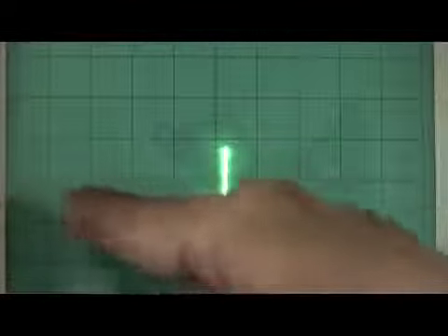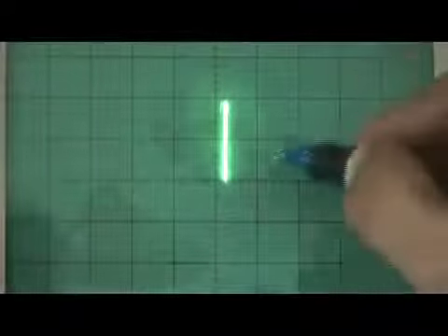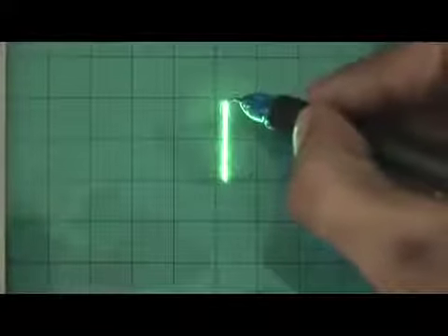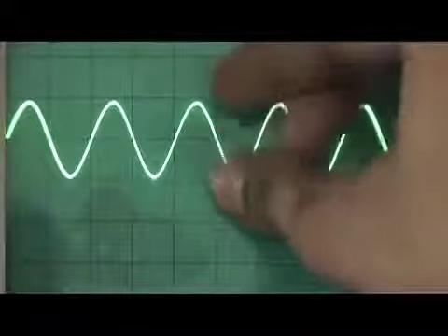Now, this dark black line which has subdivisions is your reference line. Using this y position knob you can move this line and bring it over here so that you can properly count the number of divisions. Now it is here. From here I count, it is complete till here, 1. From here it is 1.2, 1.4, 1.6, 1.8. It is almost touching 2 but not 2, so let us take it as 1.9. I release the XY.